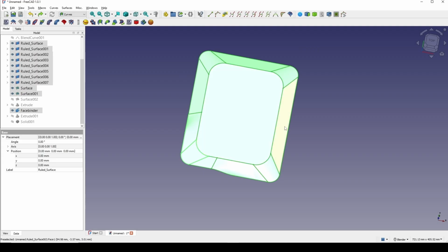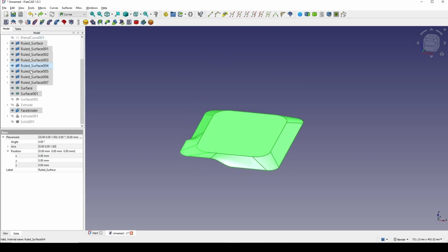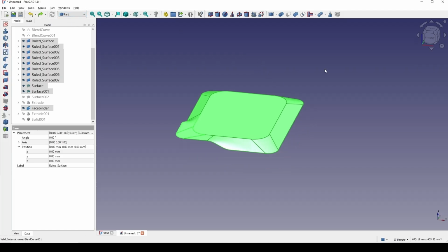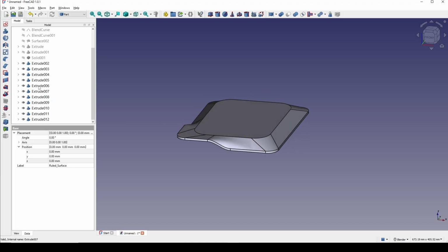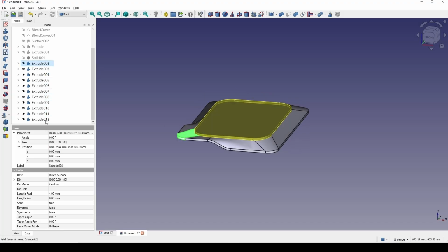The original surface. So basically I will select 11 faces and I go to the product workbench and I go to extrude this one up in the z-axis, +1, and I type in here 4, and click on create solid. Click OK. Alright, now I have 11 extrusions.